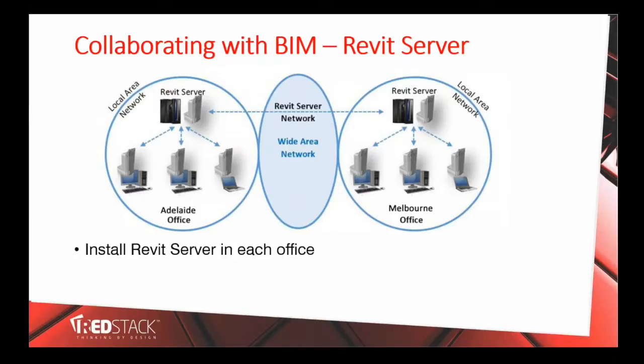This network in your offices is dependent on what role is assigned to each Revit Server. So in Adelaide, we could be playing the host and administrator role, while the Revit Server in Melbourne could be playing just the role of an accelerator, and I'll explain what those two mean a bit later on. All this means is the central files for every project would live in the Adelaide office and then would be cached or replicated to the Melbourne office. Alternatively, both servers could be set up as host and accelerator, depending on how you wish to install the product.